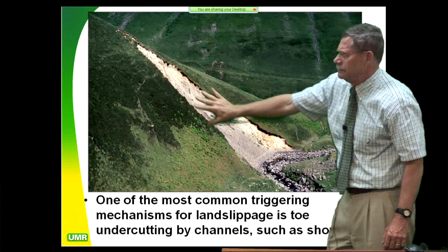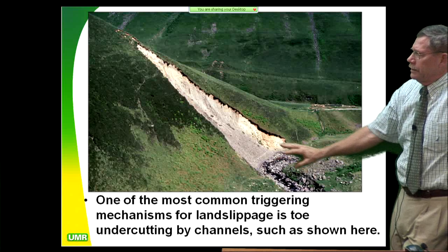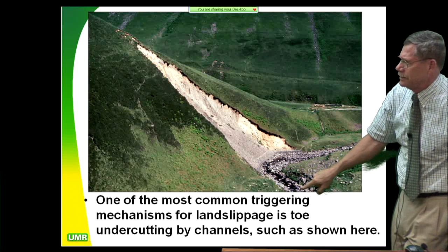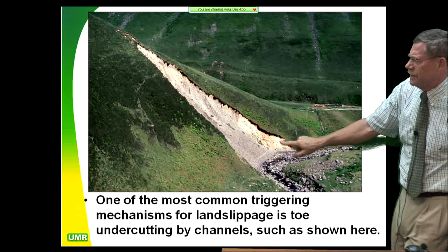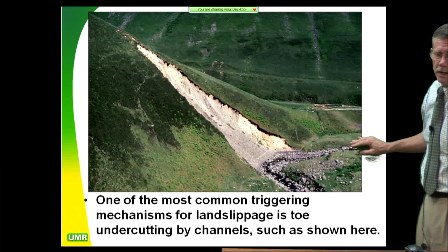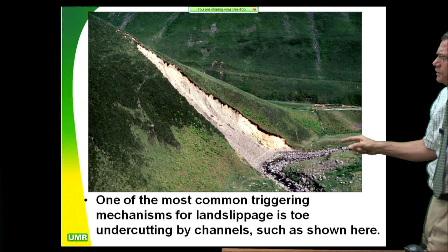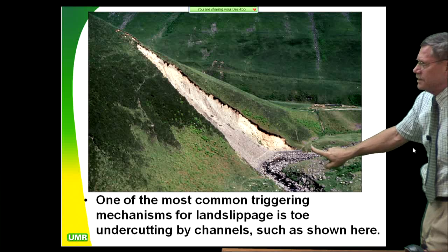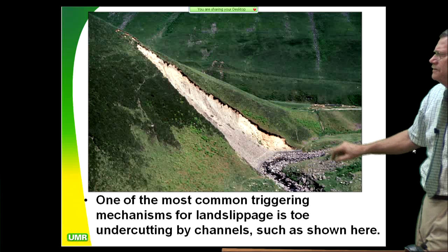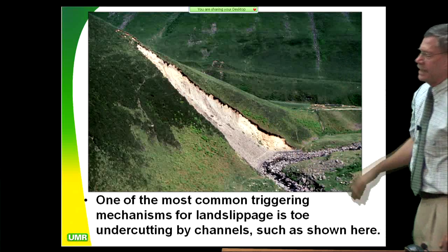When you have a landslide come down and block a watercourse, it's a very temporary feature geologically. The fine-grained material is going to get blown out pretty quickly and leave lots and lots of large diameter stuff behind. And the size of this large diameter stuff and the heights of the strath lines can help you determine how big the paleo flood Q, or quantity of water, was. It leaves behind very nice physical evidence that you can apply the standard principles of channel hydraulics to, provided you put in a bulking factor. This terrace right here is left over from the removal of this landslide dam. So it always leaves a nice terrace, and that terrace always has a steeper gradient on it than the fall line of the channel.